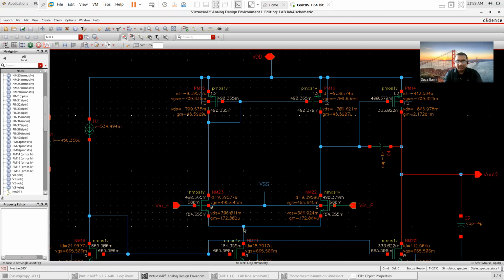It's mean if I can increase the resistance, then I can also increase the gain. If you think about a common source stage, the gain is GM RD. If you can a little bit increase in RD, the gain should be increased. You also know the resistance is inversely proportional to W. Therefore, I slightly reduce the W. As in the long run, my resistance a little bit increase.